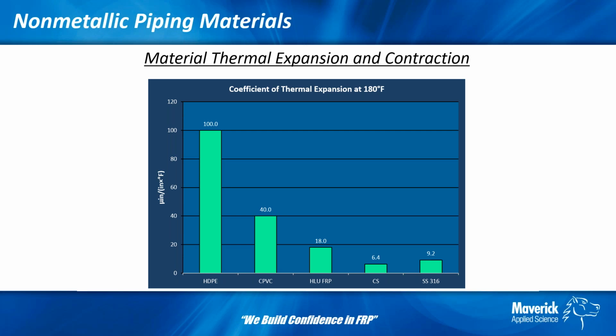The dual laminates, generally the FRP will constrain them enough to where we don't see a substantial difference in thermal expansion for dual laminates, regardless of the liner. Obviously, the key is that it has to be properly bonded.